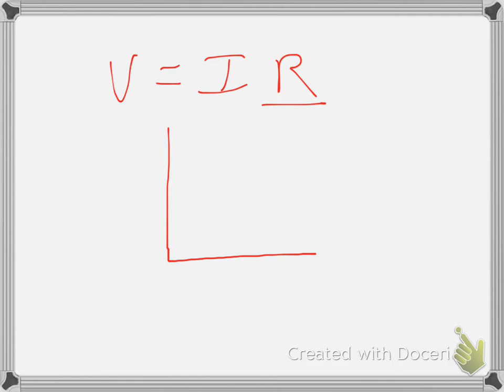In other words, if you plotted the IV characteristics in this case, I think your book uses it as IV, you would see it go along with 0, 0. You'd be increasing the voltage, but nothing would be happening. These diodes just have a voltage threshold, and then all of a sudden it just spikes up. And so that's not an ohmic material.